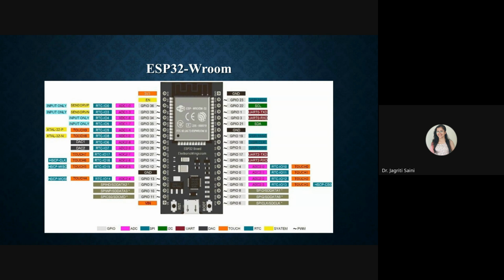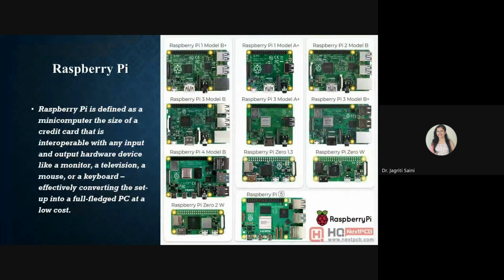And we have these GPIO pins, meaning general purpose input output. So when we have to connect input and output, that means your sensors and actuators, on any of these pins we can connect them. And this one is your USB cable connection, USB type C, we can connect over here. And then we have these RST and boot buttons. This one you may need to press when uploading your program. This one you can use for resetting the chip anytime. There are multiple grounds, and there are multiple power supply pins also. 3.3 volt you will find right here, and accordingly the communication we can establish with this.